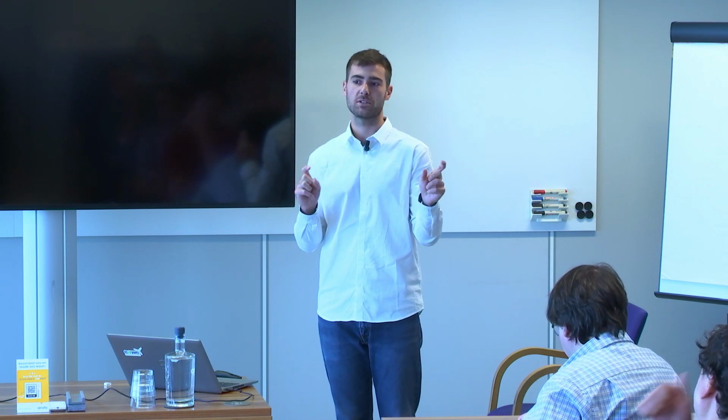the RAFT numerical model uses the static position plus an estimation of the dynamics, whereas I believe Kutai's model is time domain. I know that in the verification process of RAFT, they verified it against OpenFAST, and it has good agreement. But on some dynamic quantities, for example tower base bending moment, they had discrepancies between the two models. So maybe that's why the value of the pitch is not the same. And I guess the limit of the constraint is also up to the person using the optimization framework.